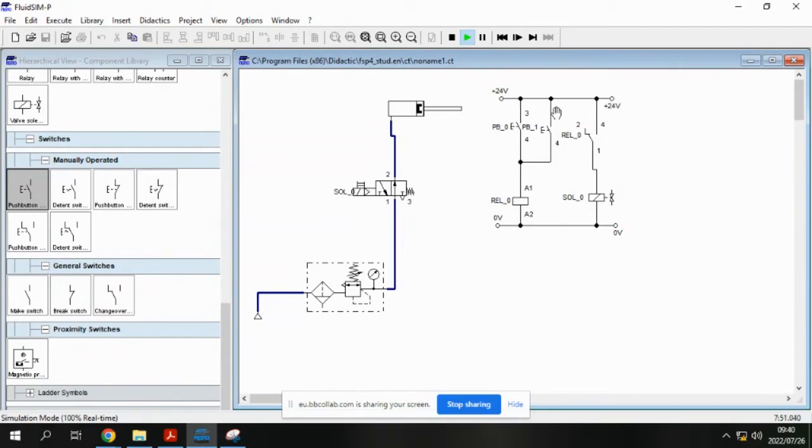265, yeah. It can push up to 265 volts. So this is where you connect your 265 volt. But you actuate it with a signal that comes from a PLC, which is around 5 volts. So those signals go in at A1 and A2.